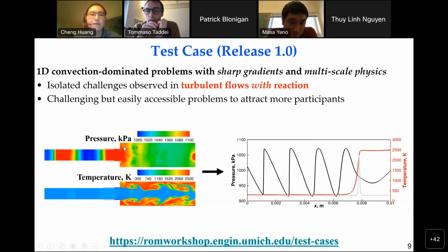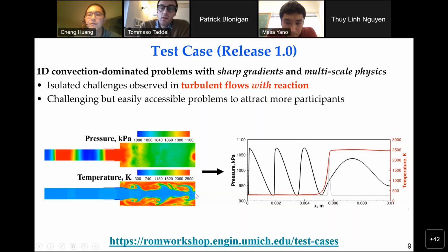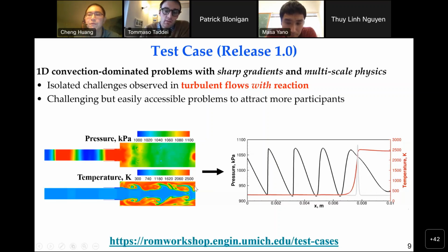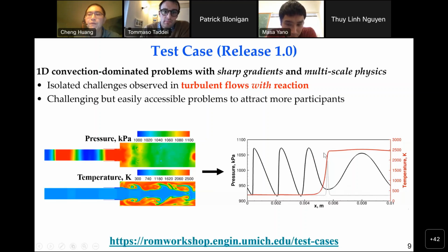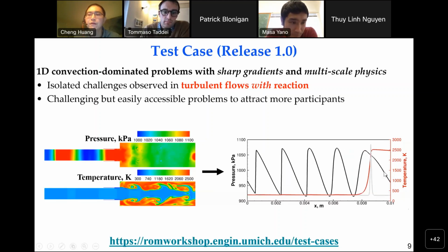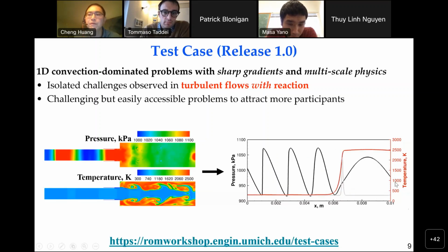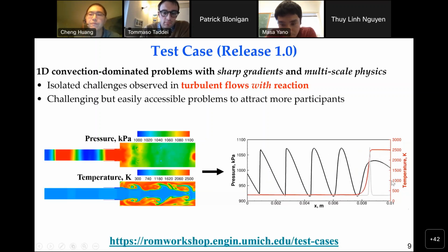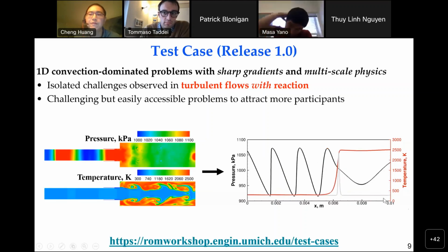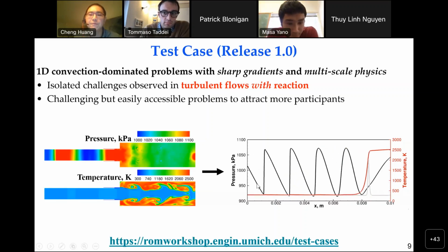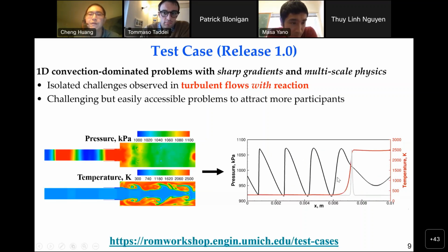And as I said, you will have pressure oscillations as well, anticipated in this propulsion system. So we are also imposing acoustic oscillations from the downstream. The oscillation is imposed from downstream. We just simply perturb the pressure at a certain amplitude and frequency. You can see this is a simple perturbation. We have non-reflective boundary conditions both upstream and downstream, and we just let the wave go out.